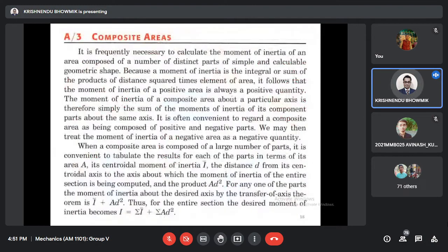Now, the way we have solved the problem for coordinate system, to calculate the centroid, we have some composite area also. In similar fashion, we will decompose the cross section into different parts, part 1, 2, 3, 4 up to n. For every case, at the centroid we will calculate Ix, Iy or Iz. Then we will use the parallel axis theorem.